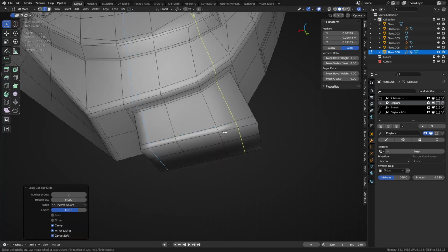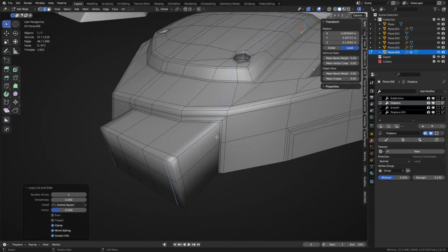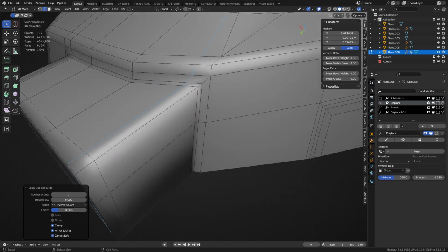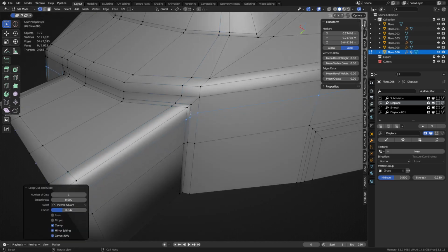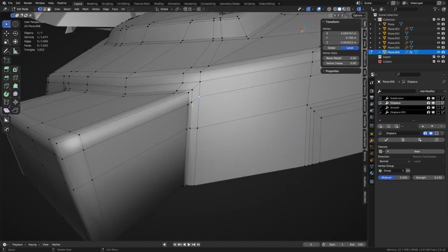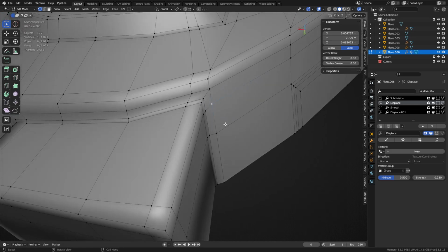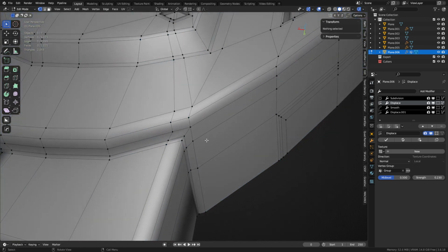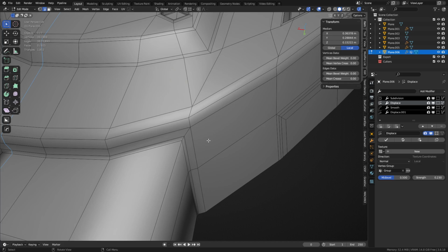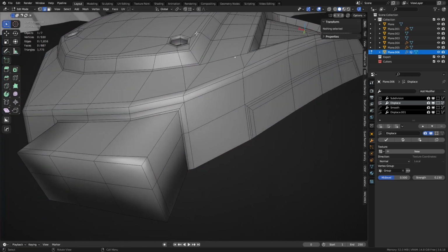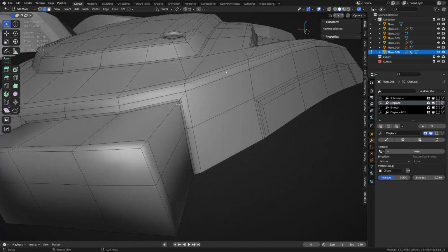If you add loop cuts, and you do this kind of similar to what we did already, just don't send them all the way across the mesh sometimes, if you don't need to. But you can do loop cuts like this. You can see these ones want to expand outwards instead of collapse back downwards. So that's going to cause a little bit of problems for us. There's ways of localizing stuff like this, but it doesn't usually work out well. So we would really want to think about where we're going to cut our edges out into and all that other fun stuff when doing this.